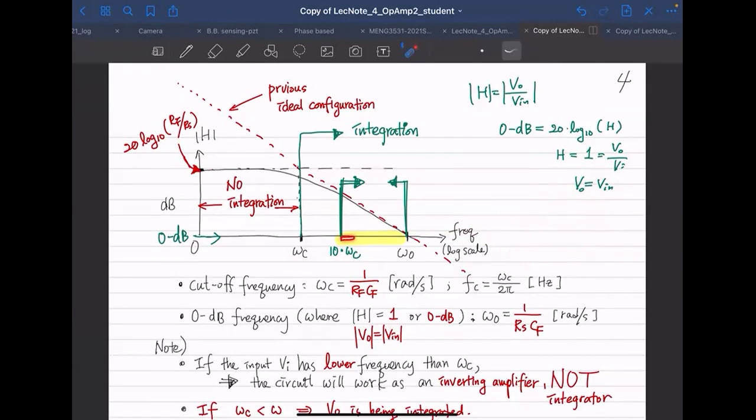So I'm going to use a frequency range between here and there, where I can still have a lot of juice coming out and it's going to be integrated. Right above the cutoff, the ideal and practical responses are getting closer, but there's still a little bit of discrepancy, so that's why I don't want to use it. If I push a little bit higher, then they really get close, and my practical and ideal are almost the same. That's the reason why, okay?